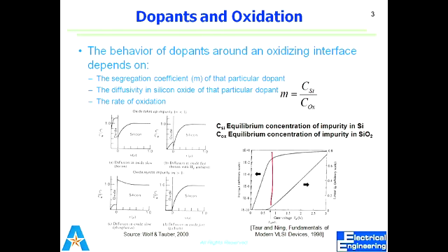If we take this case, you know that the volume of oxide is 2 times greater than silicon, right? Let's suppose that 0.02 micrometer cube is the volume of silicon that is consumed. So the volume of silicon dioxide that is produced would be 2 times of that. That is 0.04 micrometer cube.